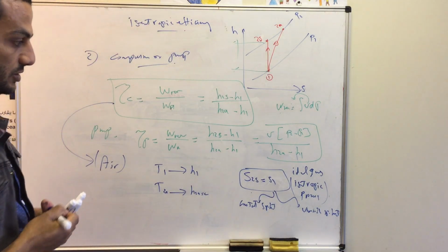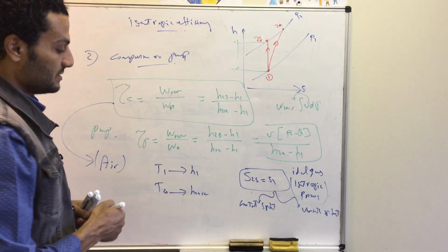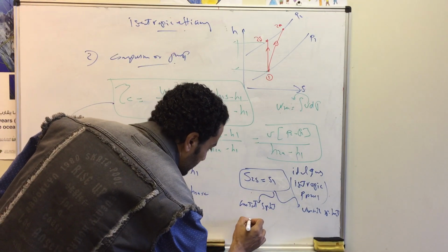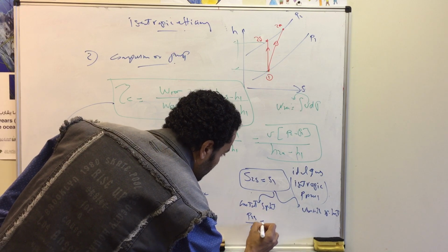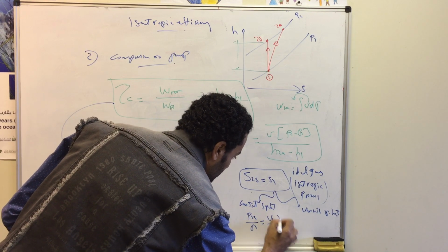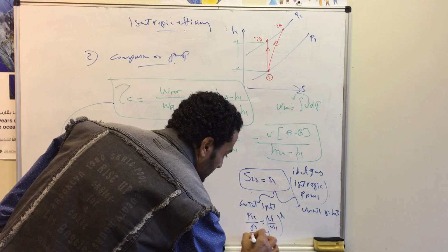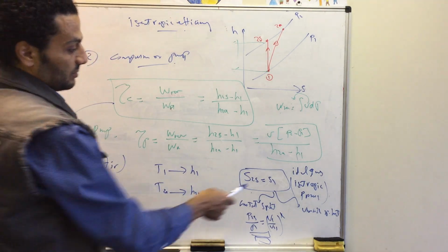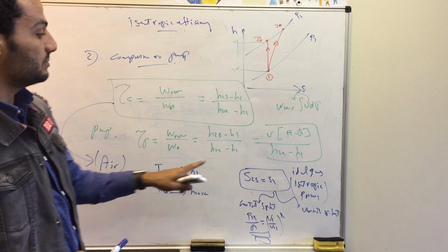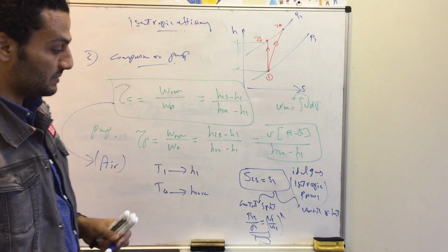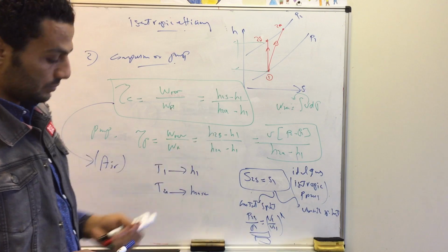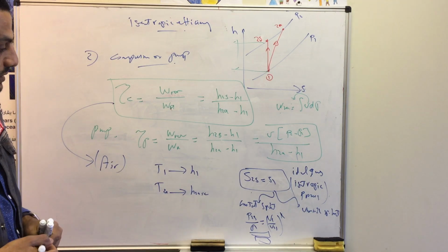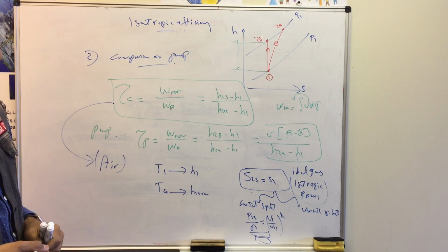Okay, so if we are asked to follow the constant specific heat analysis, we follow the isentropic relations, like T2s over T1 is the same as P2s over P1 to the power (k-1)/k, and we do have another two isentropic relations here, so we can use those relations to relate point 1 to point 2s. So if pressures P1 and P2s, which is the same as P2, are given, and also we have, let's say, the temperature T1, then we can calculate T2s. And then using this T2s, we can go to the table and calculate h2s.